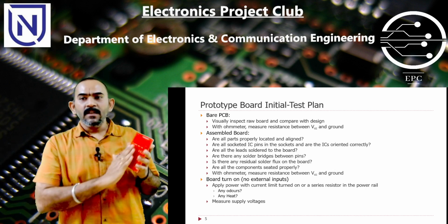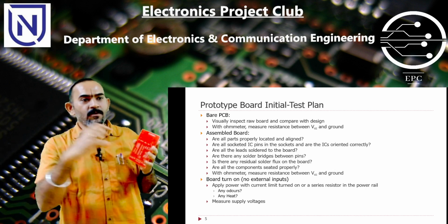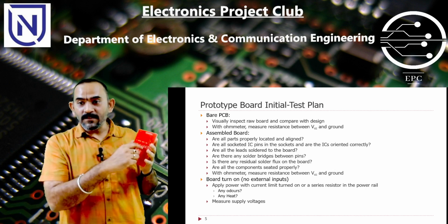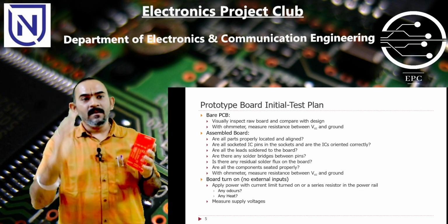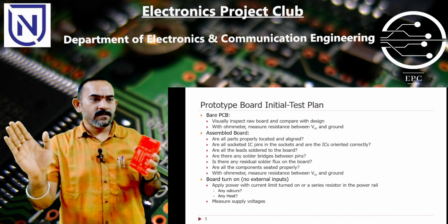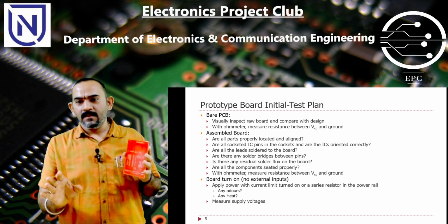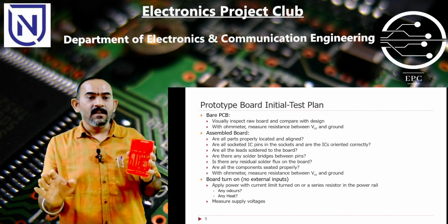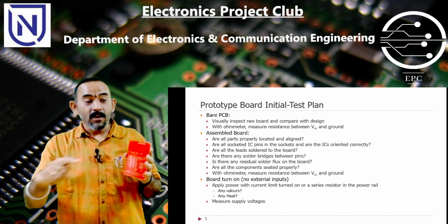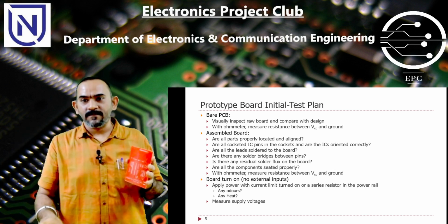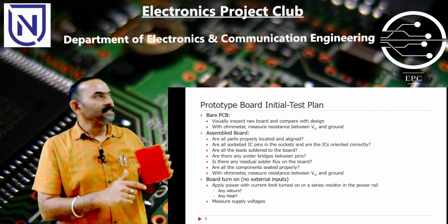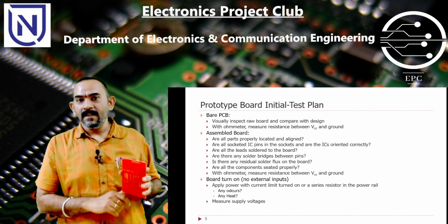Consider this case. You didn't check this, you simply put your component inside. Now because there was a short, as soon as you power on, that IO pin goes for a toss. Once that IO pin goes, basically that IC is useless now. So the cost of not detecting the fault is one IC lost. So all these things have to be done in the bare PCB itself.